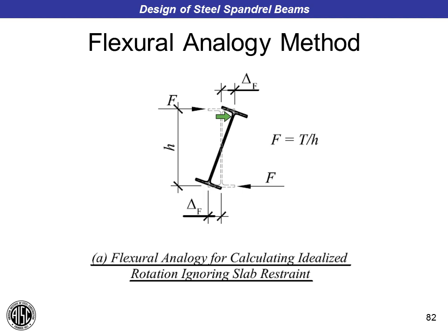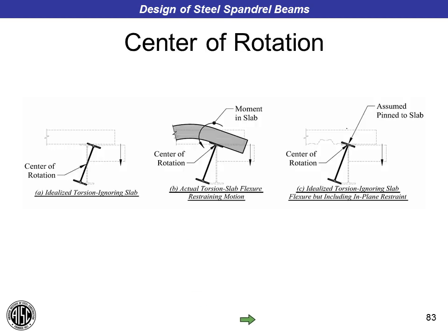And then designing that beam for just the T section above with this horizontal force applied, and the bottom T section with a lateral force applied to it. Now, this approach can be grossly conservative for long torsional spans, but as I'll get into in just a minute, it actually is relatively accurate for short torsional spans in the order of 10 feet or so.